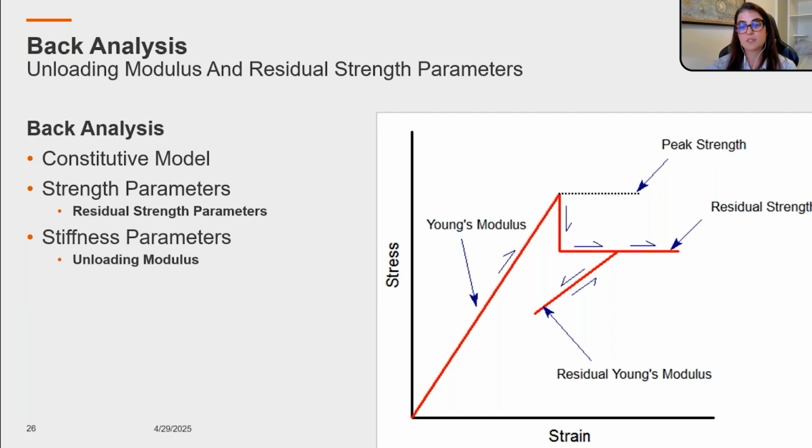And finally, residual soils are known to exhibit residual strength values that are lower than their peak strength. This is often due to the loss of cementation within the soil during loading. Therefore, accurately capturing these different strength parameters is crucial for a realistic model.